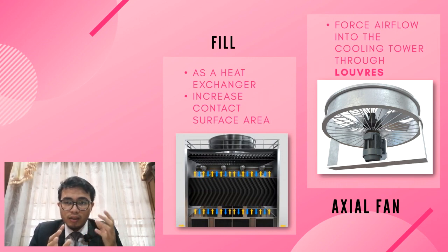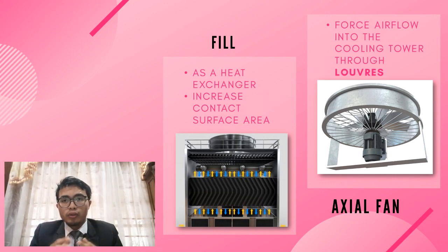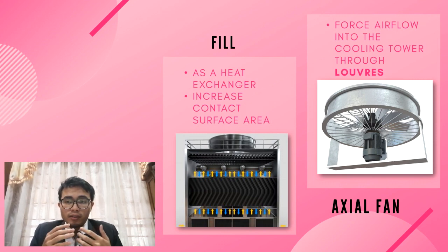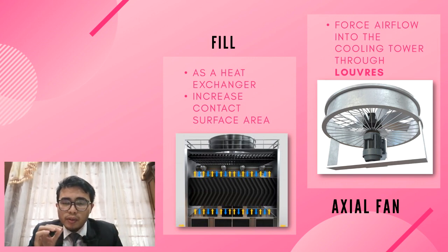So next we have the fill. The fill usually acts as a heat exchanger. The fill is actually a vital part of the cooling tower. So what does the fill do? The fill increases the contact surface area.